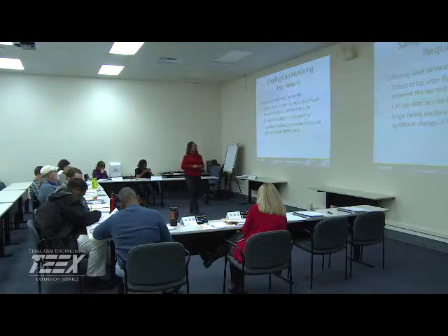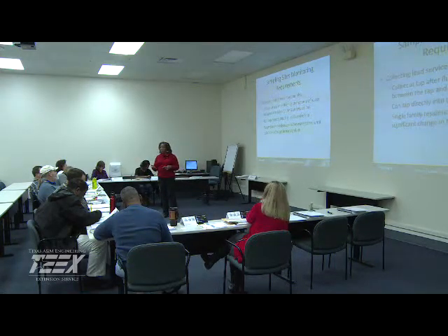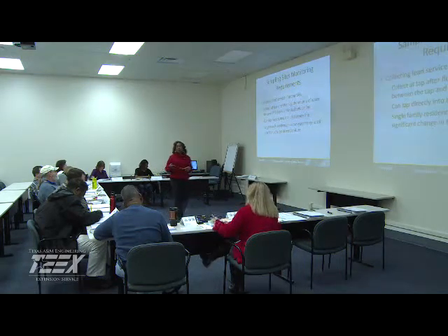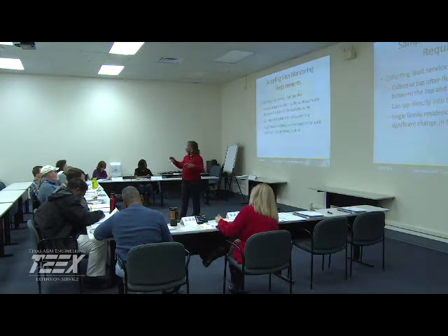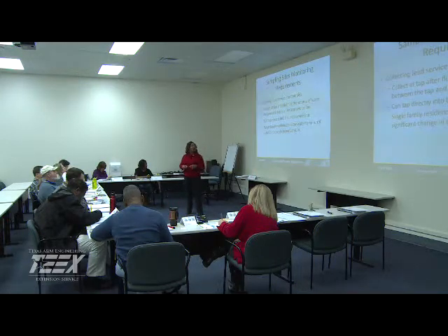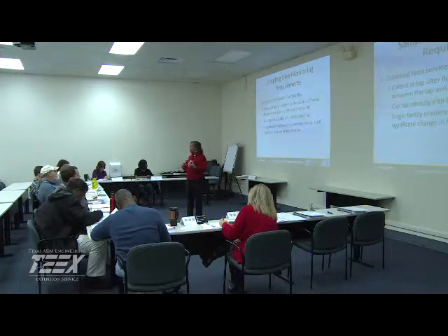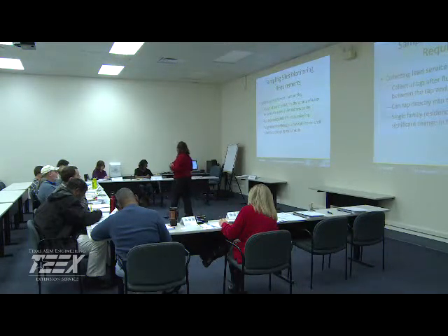All right, collect at the tap for collecting your lead service line, because we said not only are we doing the first draw, but we also want to know what's coming off of those lead service lines. So sample collection will be a little different. This time we want them to flush so we can get the actual water from the lead service line. So collect after flushing the volume of water between the tap and the lead service line. You'll give them some direction how long to let the water run if they're pulling the sample for you.